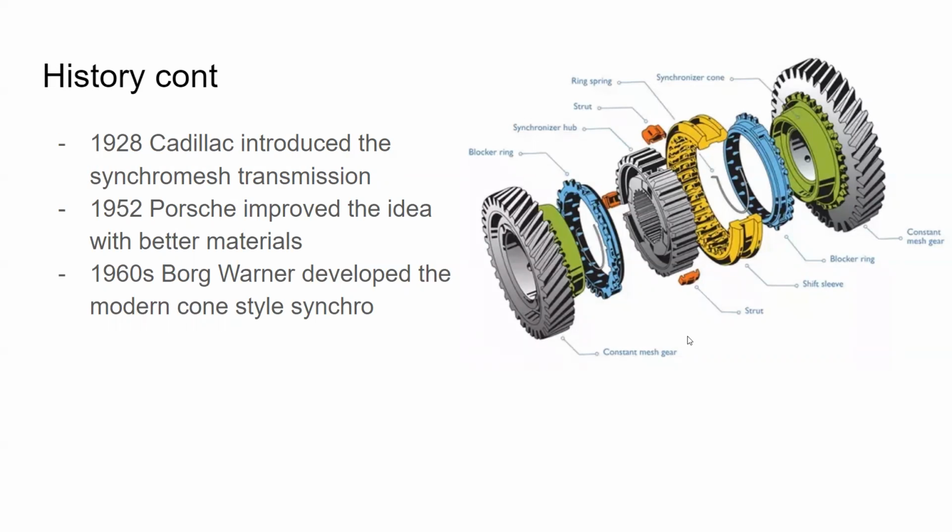So that's bad. But what they've come up with is this constant gear mesh idea where the gears are always meshed with their companion gear. And see that this gear has this smooth inner diameter on it. So it slides onto a shaft and it's able to spin freely on the shaft. That way, all of our gears can be meshed, and gears can be turning at different speeds, but because they're basically just rolling along on the axle shaft, that's okay.